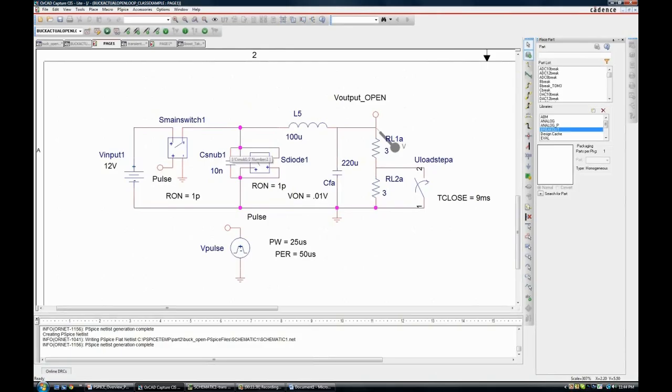And I'd like to talk a little bit about what that is. Sometimes when voltages, particularly across switches or across discontinuities, change abruptly, it drives the time step on the simulator to such small values that it'll cause a convergence failure. It's working too hard to manage it.